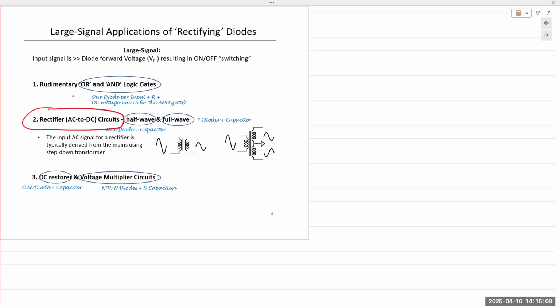And the diode rectifier circuit forms the most basic, most fundamental, and the first step in rectification from AC to DC. The simple reason is because a diode is a one-way device. So when you apply an AC signal that pulsates from positive and negative values, it'll only conduct in the direction that it's configured. So if the anode is connected to the positive of the power source, it will conduct in the positive cycle. If the cathode is connected, then it will be the negative half cycle.